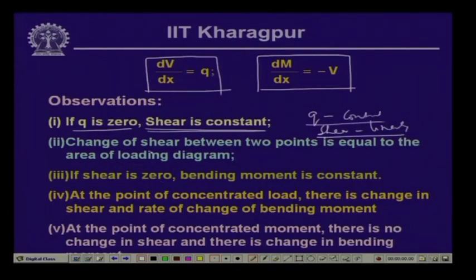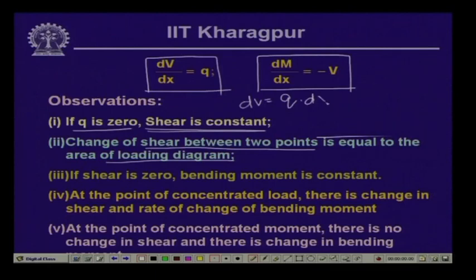Also, the change of shear between 2 points is equal to the area of the loading diagram. Now, if we look into this part of it, from this particular equation we can write dV equals q dx. Now, if we integrate this expression between 2 points, supposing we take 2 points on the beam, let us say this is A and B at a distance apart, and we would like to find the change in the shear force between A and B. So, integral dV from A to B is equal to integral from A to B of q dx.